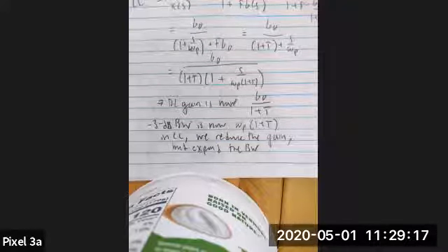And that kind of makes sense, because if we have a gain on the order of a couple thousand, we can't really use that in most applications, just because our output is limited by the output swing, which is directly constrained by the VDD or VSS of our amplifier.